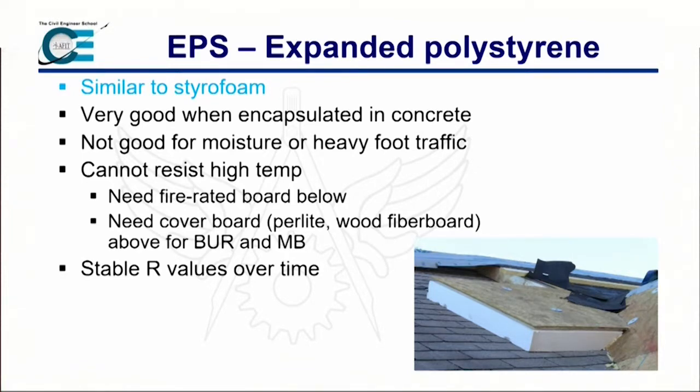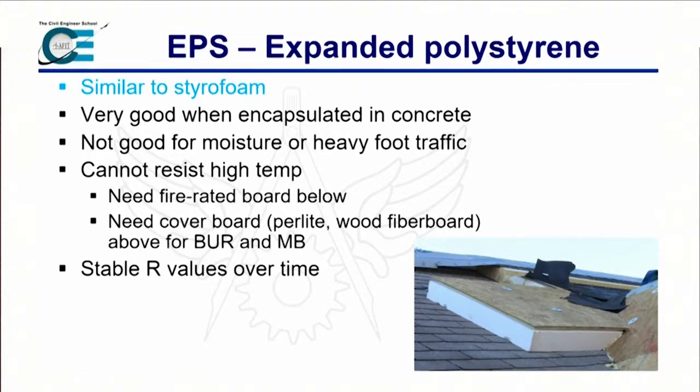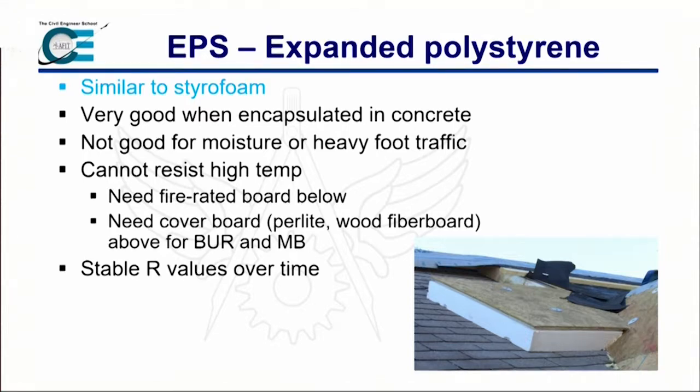So that first bullet there is probably the easiest to actually remember this. This is very similar to styrofoam. Great when we encapsulate it in concrete. Typically what we're going to use that for. That is probably the insulation of choice when you're going to encapsulate an insulation with concrete. Not so common with ISO board.